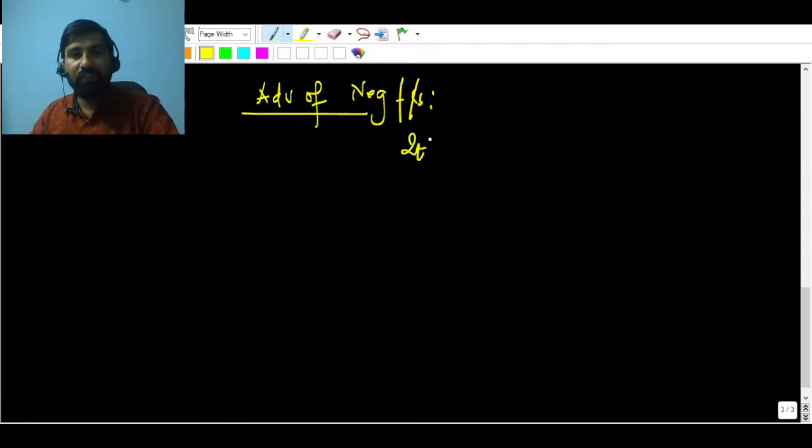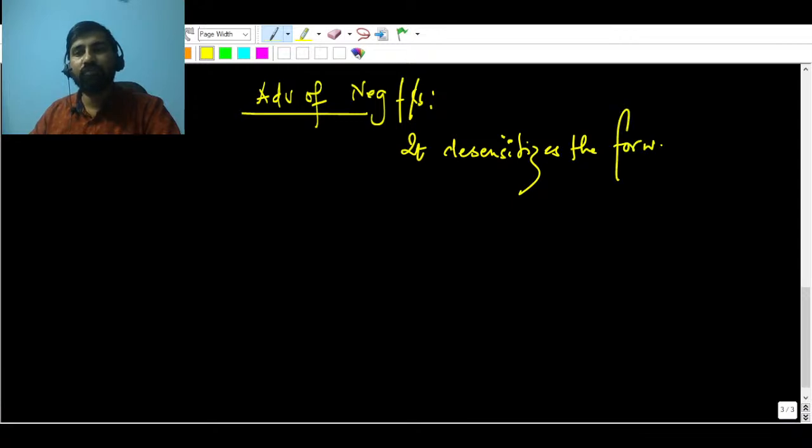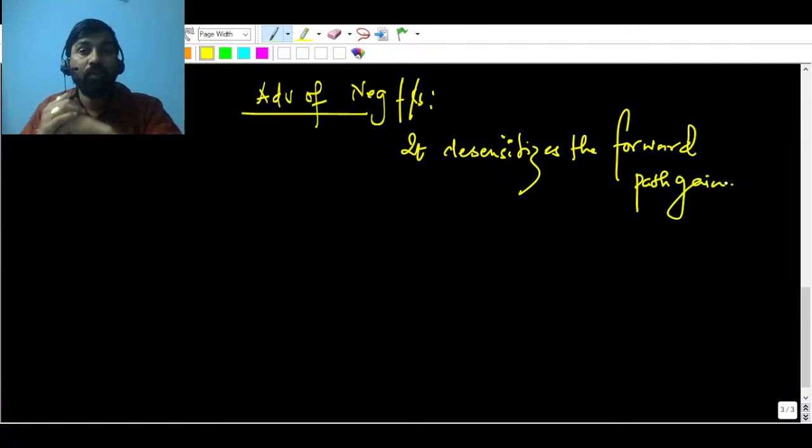It desensitizes the forward path gain. What does it mean? If there is negative feedback, always keep in mind that your loop gain should be far greater than 1.